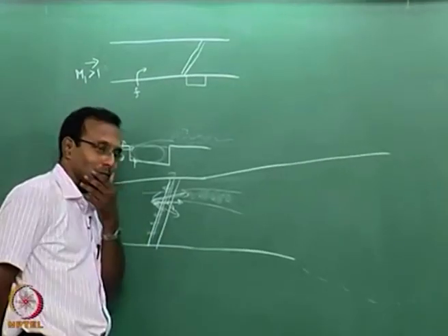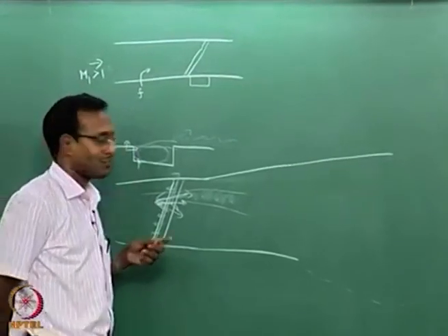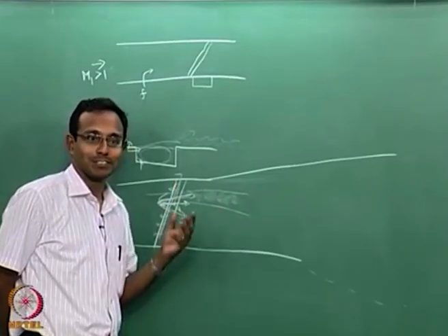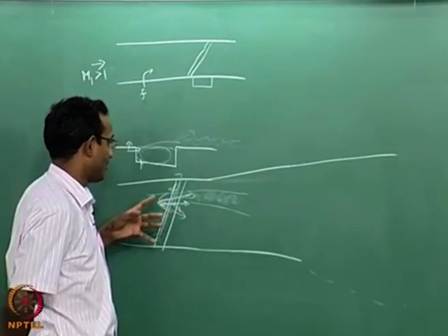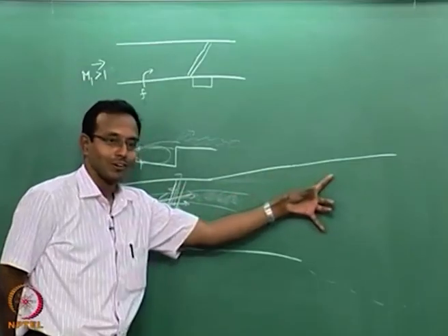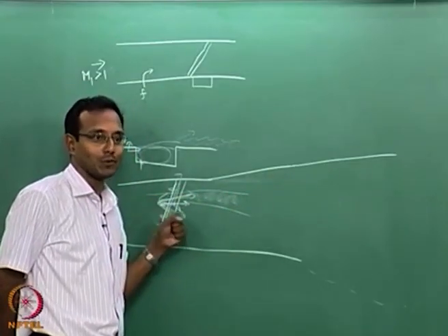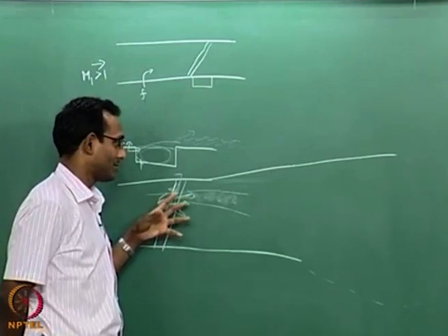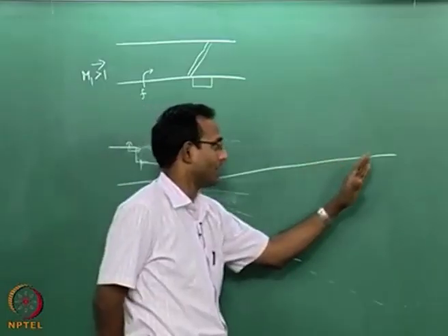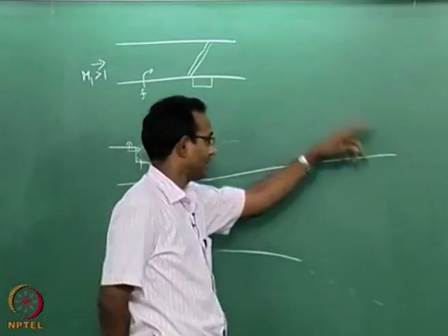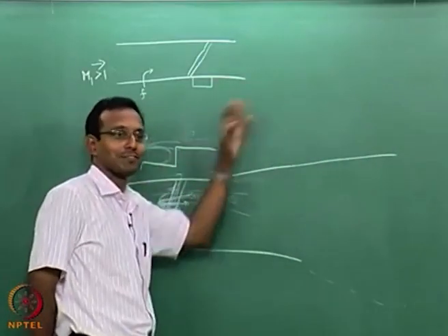There is one more problem with supersonic combustion: the flow is going extremely fast and combustion is slow. So now I have to think about the combustor being long enough to release all the heat of the fuel before this fuel air mixture gets out of my area of interest, that is, near my engine, near my scramjet.